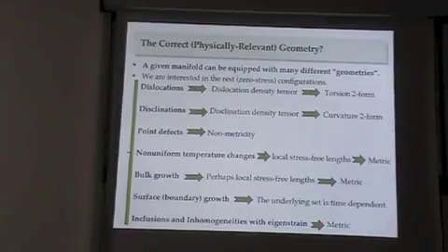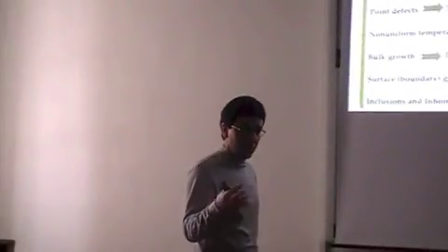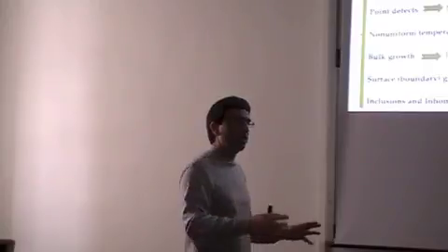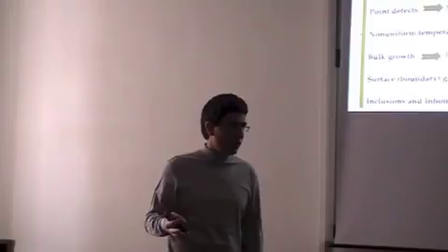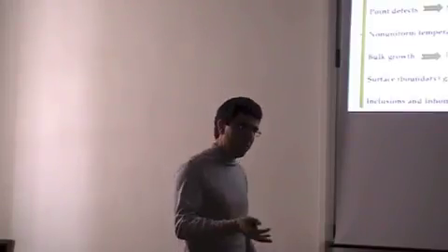So when you have eigenstrains, you could directly write down the material metric. For defects, you have to do some more work to find that, but here your idea is to introduce a metric in the reference configuration which is evolving. If you have temperature, then you have the heat equation, and yes, it will evolve. But here for inclusions, I'm going to assume that there is this given eigenstrain distribution. What is this residual stress? Of course, if that evolves, this will evolve too.